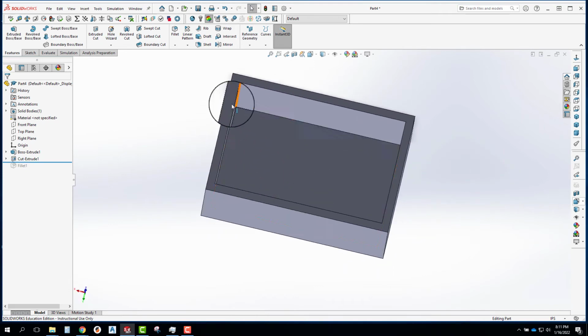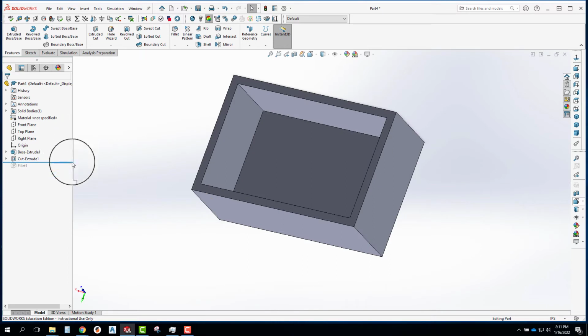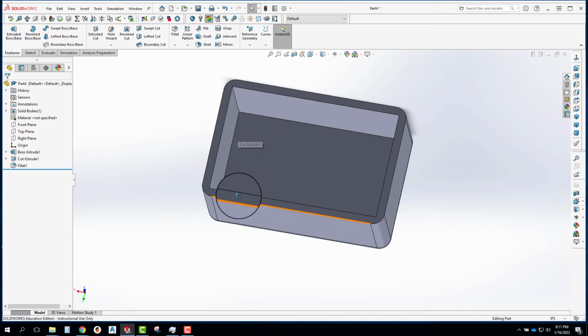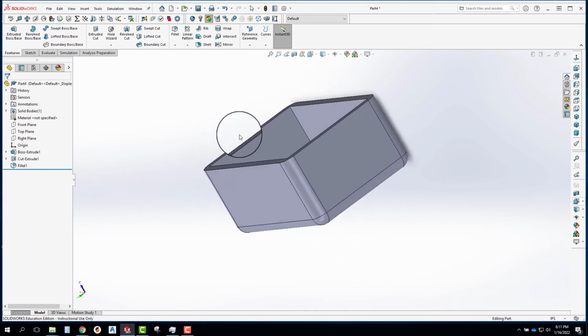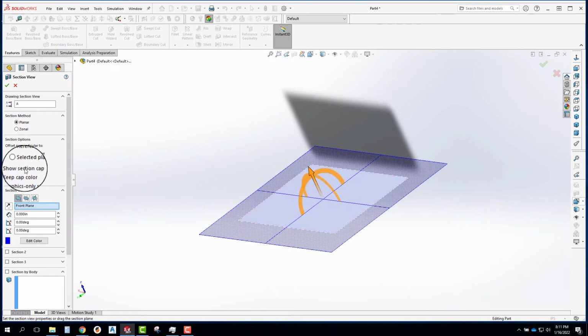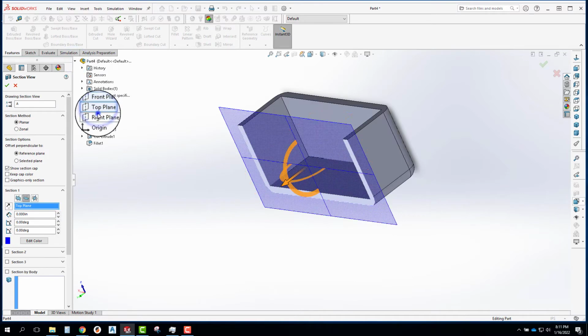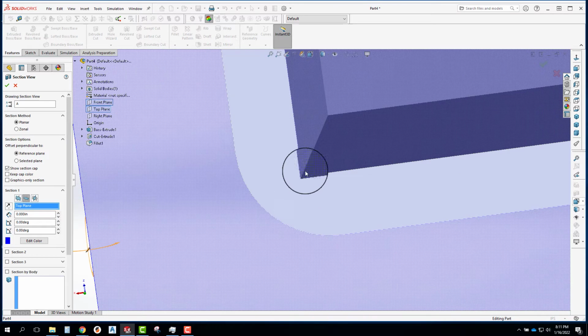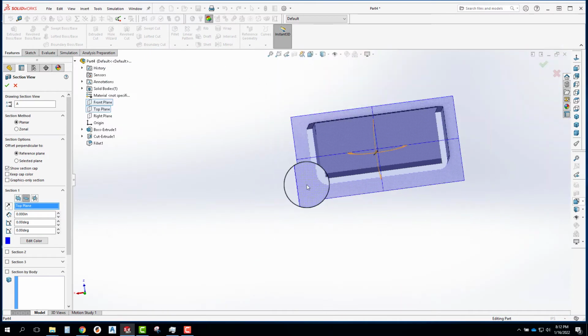But that would be a lot harder to do if I had all these fillets in here, right? When I do it now, it's going to kind of mess things up on the inside, and I don't have consistent thickness across the bottom now. If I look at a section view through it, you can see there that at those corners, it's not an even 1/4 inch wall thickness.